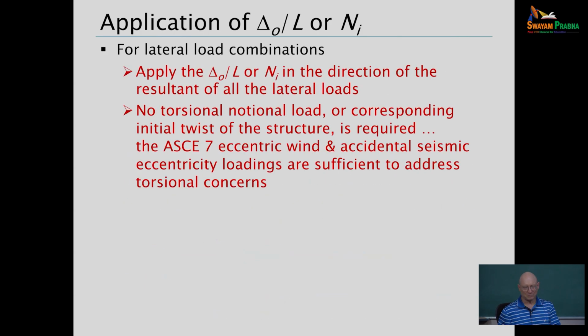Now for lateral load combinations, in your standard, you don't apply notional load at all. In AISC, for most frames, we don't. But if it's a structure where the side sway amplification is relatively large, basically if B2 is larger than 1.5, then the AISC standard says that frame is going to be tricky.